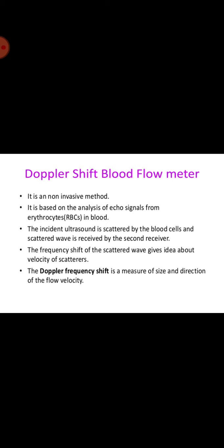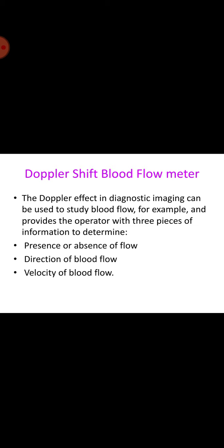Here an oscillator operating at a frequency of several megahertz excites a piezoelectric transducer, and this transducer is coupled to the wall of the exposed blood vessel and sends an ultrasonic beam with a frequency of F into the flowing blood. A small part of the transmitted energy is scattered back and is received by a second transducer arranged opposite the first one. Because the scattering occurs mainly as a result of the moving blood cells, the reflected signal has a different frequency due to the Doppler effect.